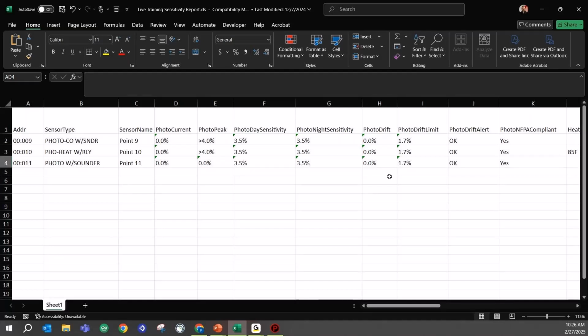When they see something they interpret as smoke, they're going to expect that to keep moving. So that little pixel that it interprets as smoke should keep moving. If that does not move over a certain number of sample cycles, the detector is going to assume that it is not smoke, that it is dirt.